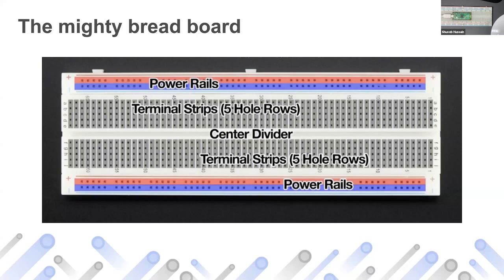I just want you to understand that this is how breadboards are connected internally. In between, they are all vertically connected columns, and one column is not connected to the other. You understand that, right? Whereas here it's connected from end to end. We'll see why that is useful.